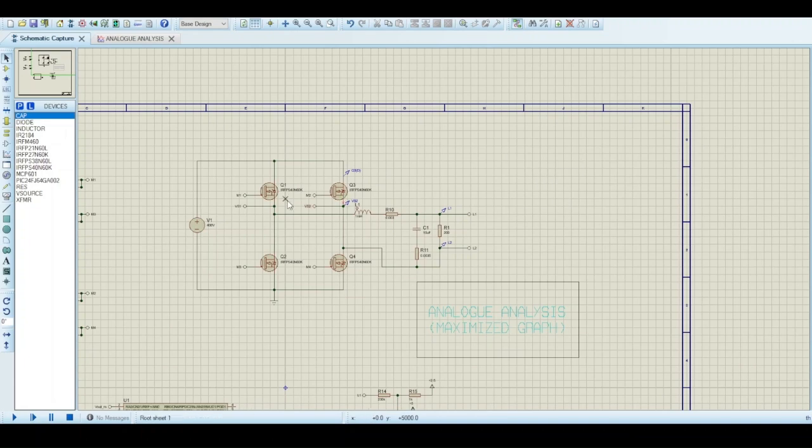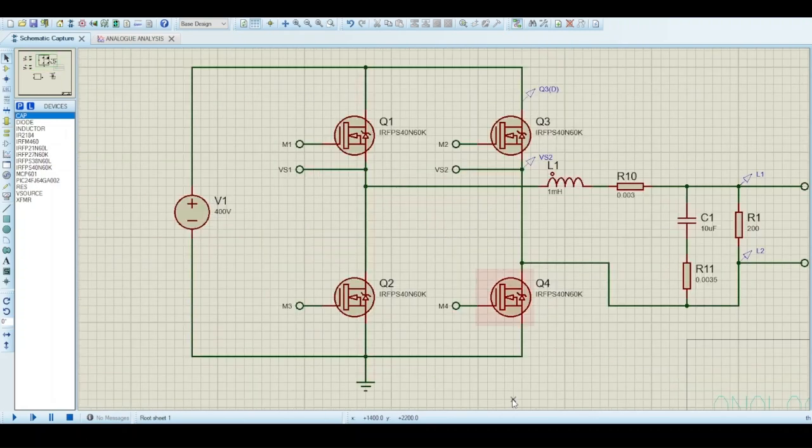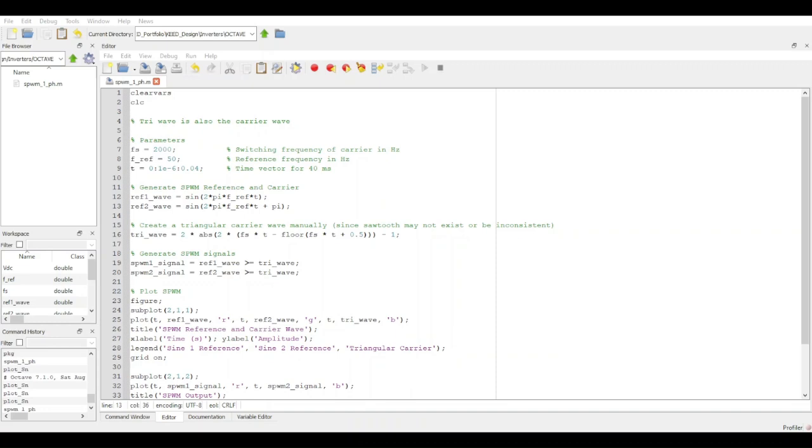All right, now moving on to the general theory of how an inverter operates. The purpose of this script is to visualize what's going on over the reference period. The reference period is determined by the reference waveform, which is the sine wave. In this script, I'm describing the triangular wave as the carrier wave, because the carrier waveform is a triangular waveform. It could be a sawtooth waveform, because it determines the switching frequency of the MOSFETs or IGBTs, depending on what you use. I'm just going to use those interchangeably.